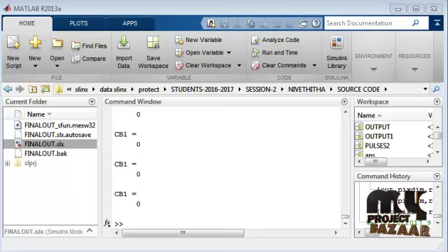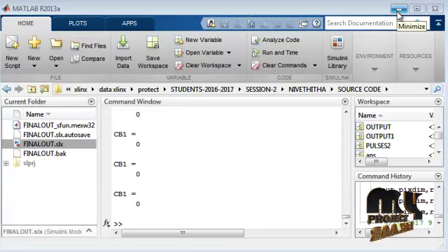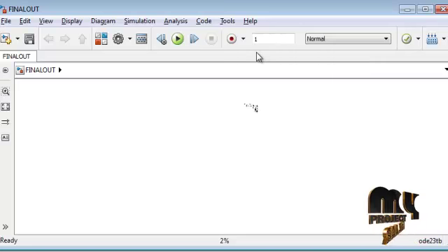Next we see the running process of our project. This proposed implementation is done in the MATLAB simulation environment. First open the MATLAB window and create a new model file. After creating the new model file, we arrange the elements as per the circuit diagram from the Simulink library browser. In the library browser, various blocks are available. Our core blocks are SimPowerSystems and commonly used blocks. From those blocks we get the elements and arrange the circuit as per the base paper. After arranging that, we click the run icon. The corresponding scopes show the output of voltage, current and such parameters.